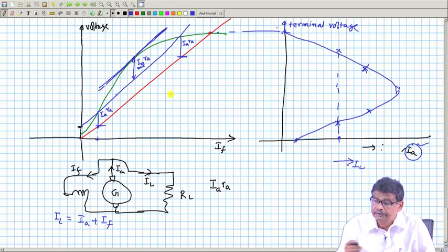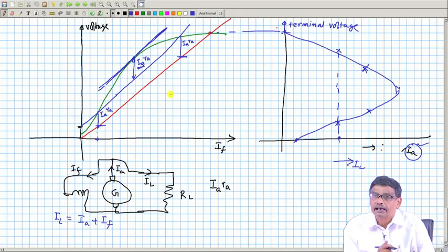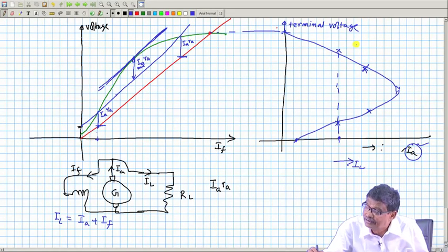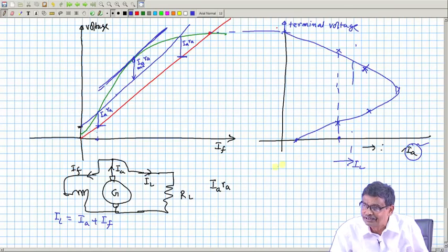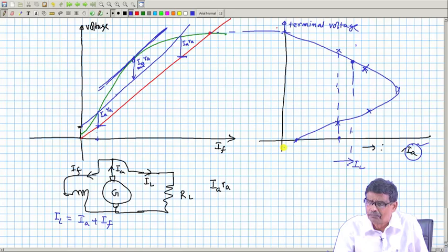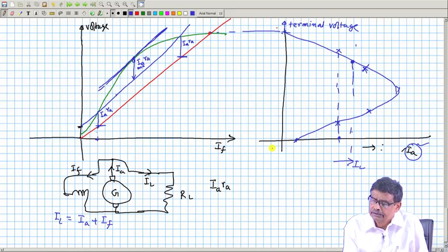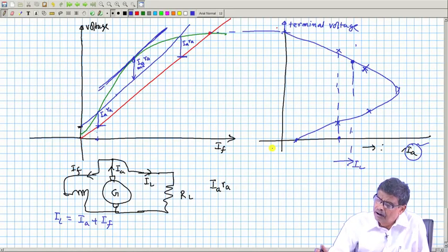Therefore, this is the story of a shunt generator, where I have explained both open circuit characteristics and load characteristics. Here also from no load to full load. Of course, full load will be here, do not worry about that. I will not go to this extent or things like that. Whatever is the rated armature current, corresponding to that I will get this point only. These points are unstable points. If you short circuit it, it will straight away come here. But what I wanted to tell you, it will perhaps traverse a path like this. Therefore, up to IA rated you will go and it will come here.